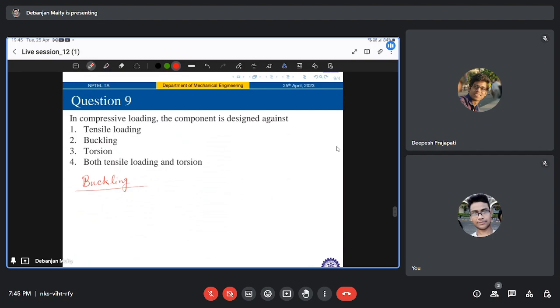So in terms of bending theory, what can you tell me? What is the equation? You have M by I, where M is your external bending moment at the section, and that is equal to E by R, which is equal to sigma x by y, right? What is sigma x?